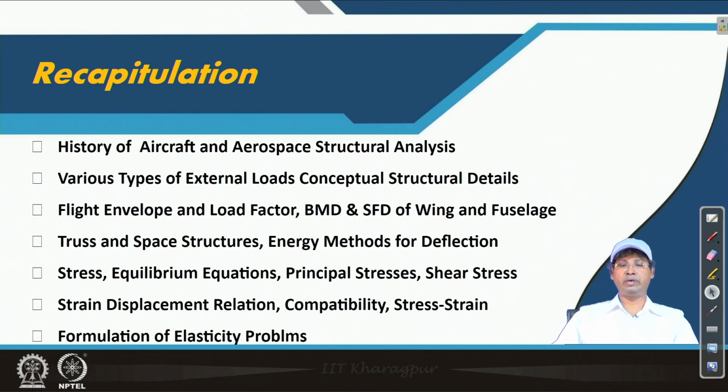The maximum possible amount of fuel is stored inside, and because of that the wing bends down. How much the tip bends down, and how close the engine comes to the ground, becomes important. So we need to find out deflection.